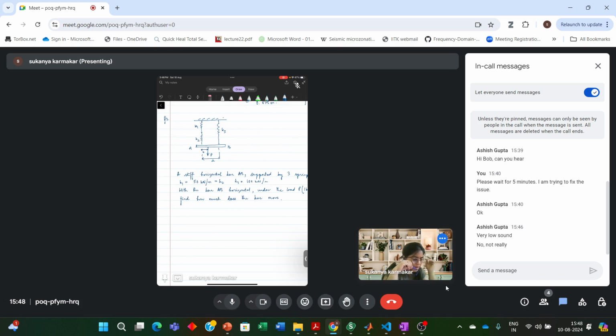simplify the system. Since the springs K1 and K2 are in series, they carry the same spring force, with different amounts of elongation in each spring. If the elongation in spring 1 is delta 1, then delta 1 plus delta 2 will be the total deflection.